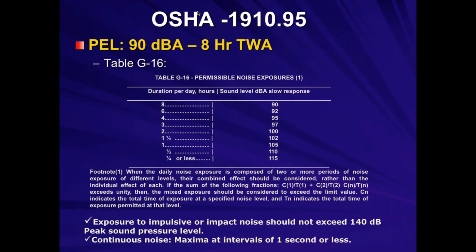exposure limit. If you don't have very sophisticated devices available, even on a sound level meter, you can probably store a reading every minute, and you can download it to software, and you can calculate the exposure over 8 hours, and so on and so forth. We haven't always had these kind of tools available to us.